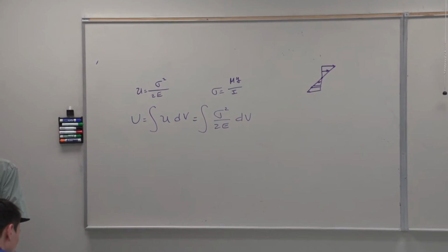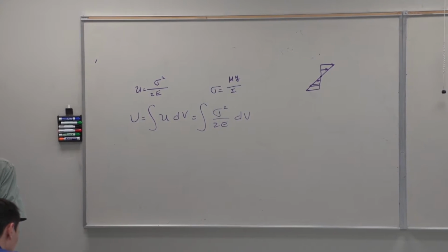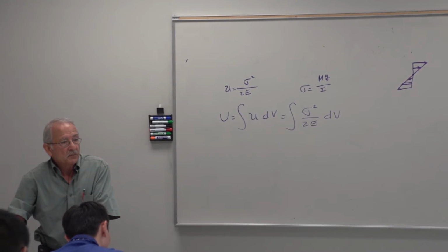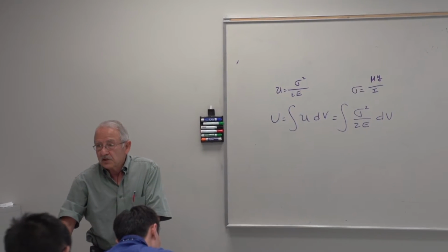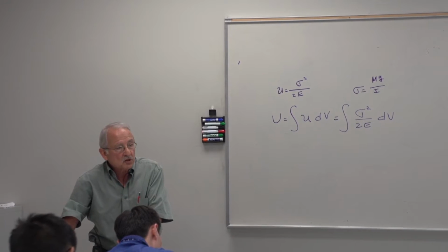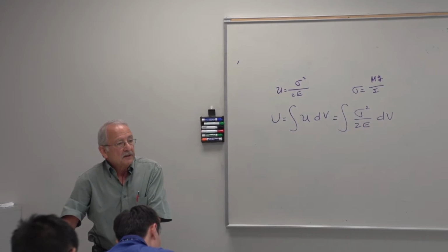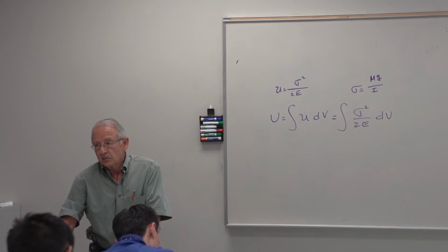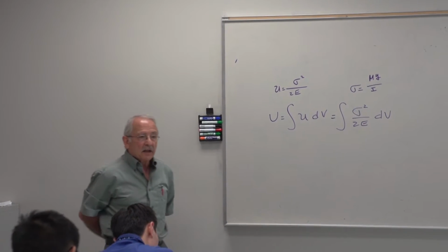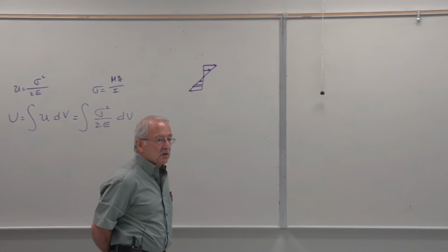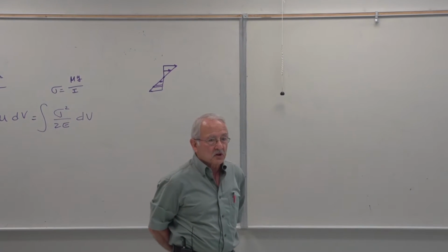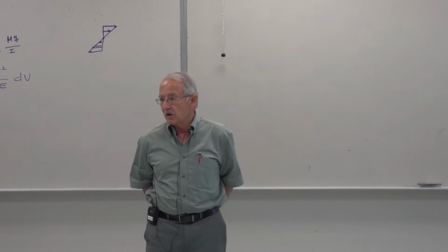In general problems, you may or may not have a constant bending moment. Although the equation is derived for a constant bending moment, it gives you good results provided that the beam is long, meaning that the length of the beam is at least 10 times the largest dimension of its cross-sectional area.